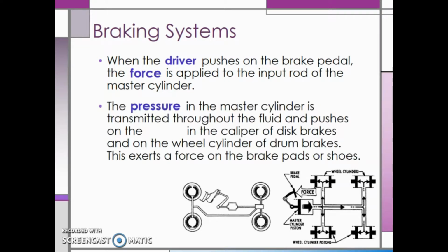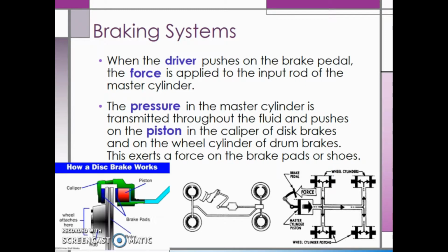The pressure in the master cylinder is transmitted throughout the fluid since the pressure stays constant in a closed system. The fluid then pushes on the piston in the caliper of disc brakes and on the wheel cylinder of drum brakes. This exerts a force on the brake pad or shoes. This force causes the piston to move out towards the rotor, pinching it, which causes your vehicle to stop.